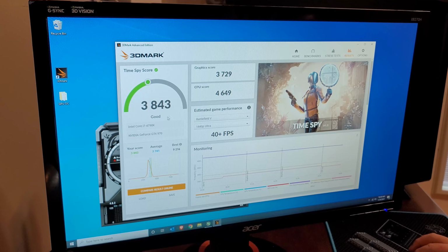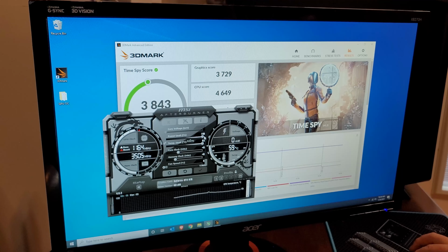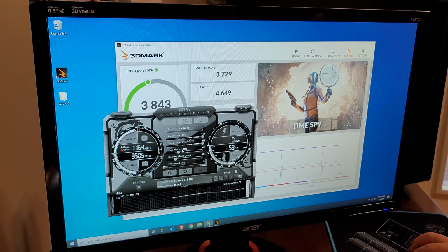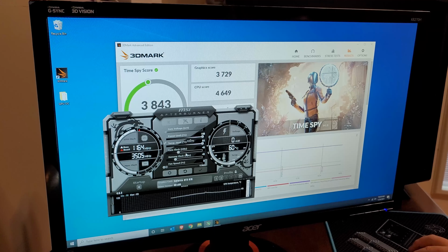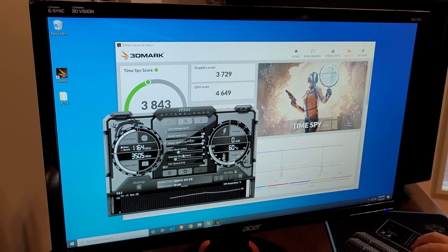So just that in itself, this is the kind of overclock that you can do now. And if you just move the power limiter to 110 and leave it at that and save your settings, you have an overclock that's probably never gonna fail. So the overclocking really gets down to when we're doing the core clock here. And when we're trying to move this slider up to bring up the core clock, and then what we'll do second after that is bring up the memory clock.